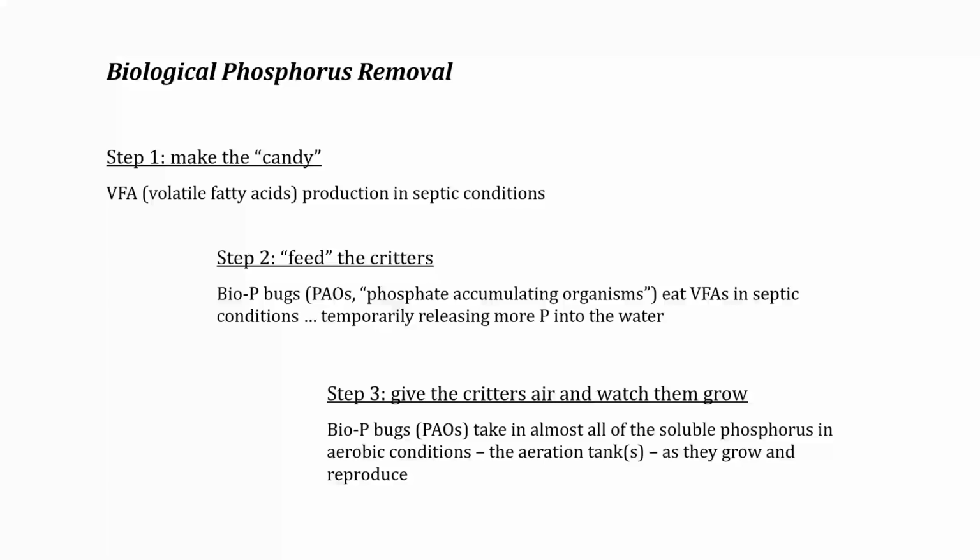If the pH drops down to 6.75, biological phosphorus removal stops. If it drops down for a day, that day you're not getting biological phosphorus removal. Comes back, then the next day you will. If it drops down there too long, you're going to kill off the organisms. You've got to start all over. Give them enough air.